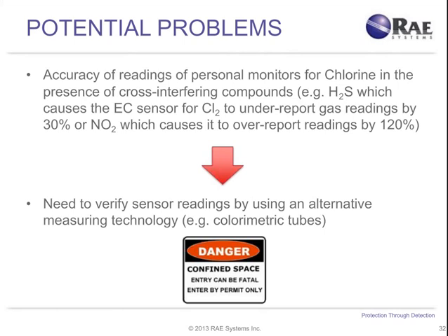So in a situation where, let's say, there is a person doing maintenance on a chlorine tank, an empty tank that needs to be painted, repaired, or welded on, imagine that this tank was sitting empty for some time, and then a rat accidentally fell into that tank. A decomposing body of a rat can produce a lot of hydrogen sulfide, actually up to a deadly concentration.